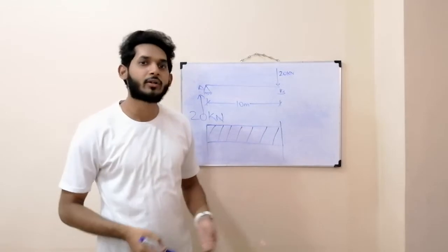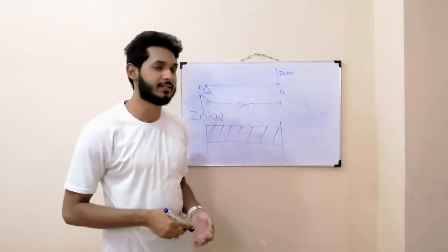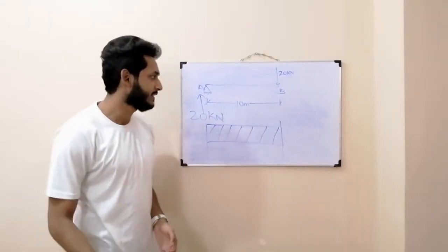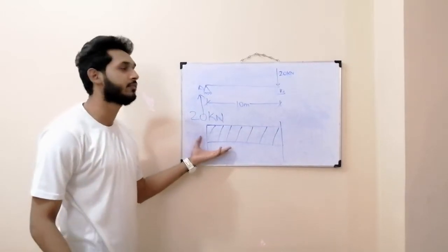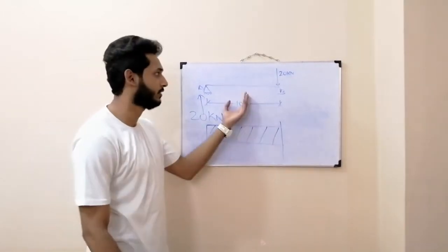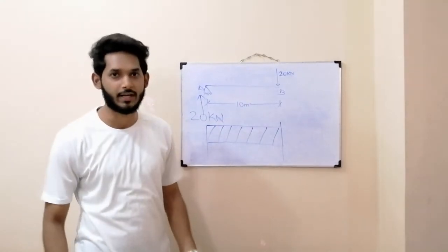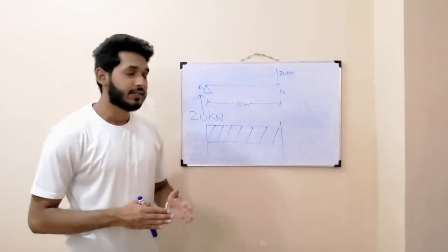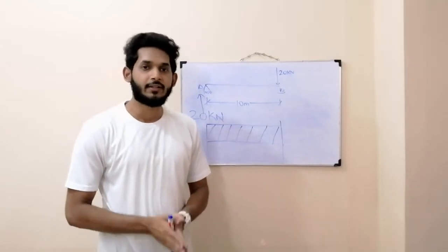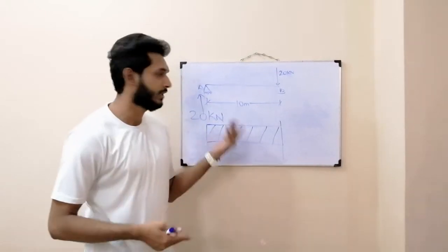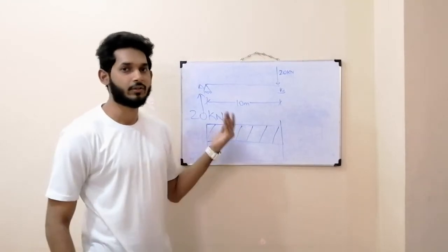And then the employer looks at you with a derisive look on his face and says, you are rejected. The reason is because there was no shear force diagram that existed for this beam in the first place. Why? Let's see. The first thing that we need to do for any beam or frame is find the degree of indeterminacy. So let's work out the degree of indeterminacy for this beam.